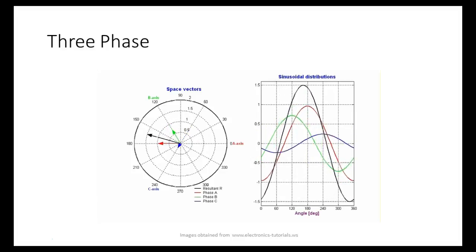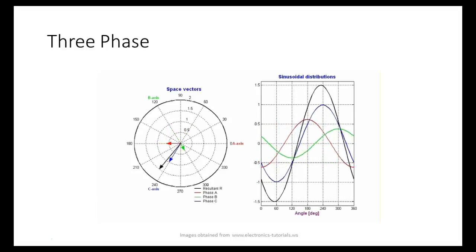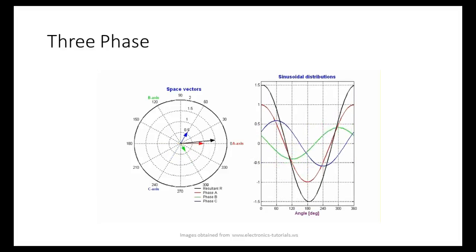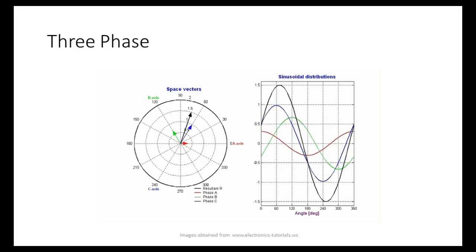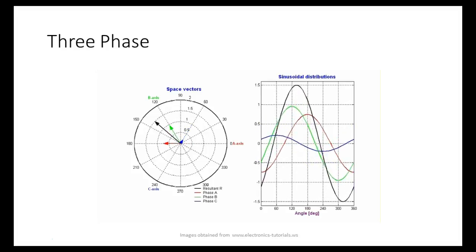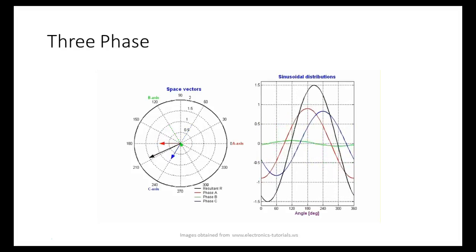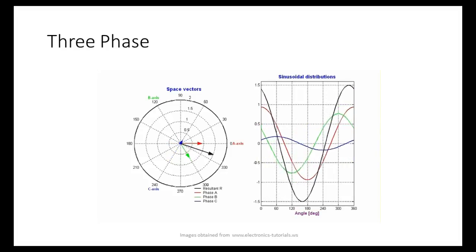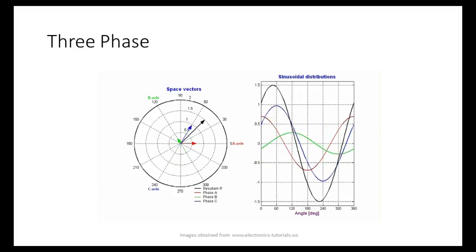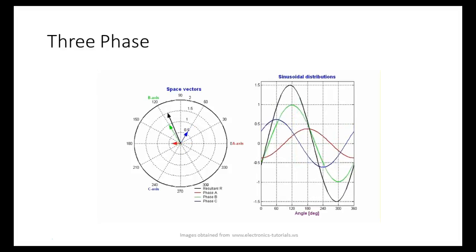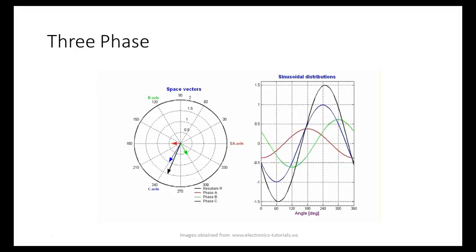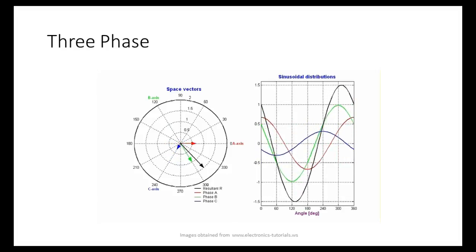Yeah, but we're talking about three-phase motors. You're talking about single-phase loads. So when we were in motor controls and you hooked up your transformer, we tried to get y'all to use different phases on the transformer for your single-phase loads.